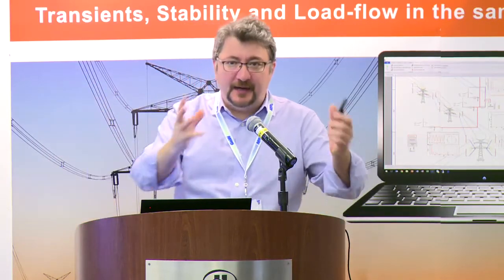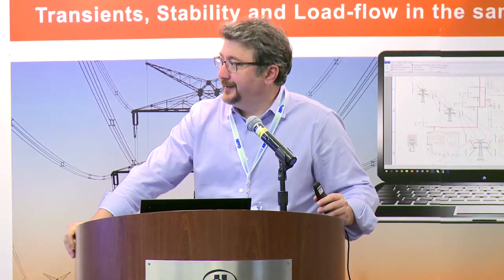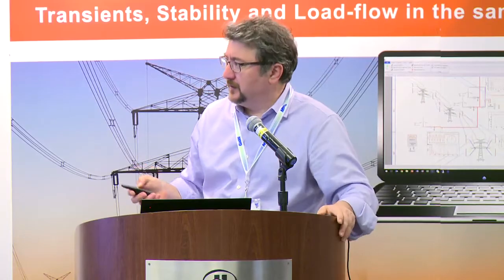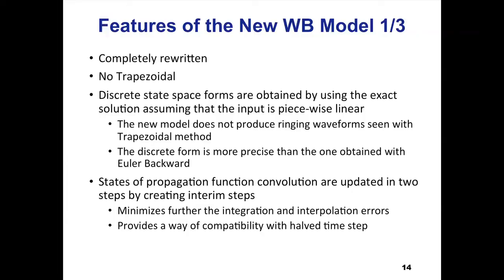Then we combine the solutions, and this way we can really handle short lines in wideband model. This was not possible before. There is another detail about the eigenvector switchover, but I won't talk about it. It's just regarding transformation matrices and eigenvalues, but not very important.